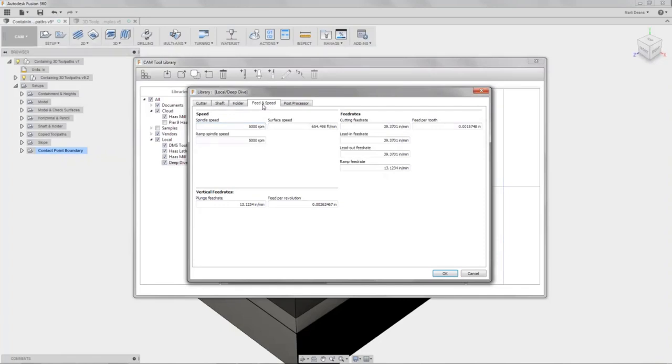feeds and speeds. So for example, our Haas mill goes to 12,000 RPM, and I usually am cutting aluminum, which like 3/1000 of an inch is probably fine. So maybe this is a good starting place. Maybe if I'm really roughing stuff out, I want to go to like 4 or 5. Maybe this is my good starting place. So it depends on the tool.